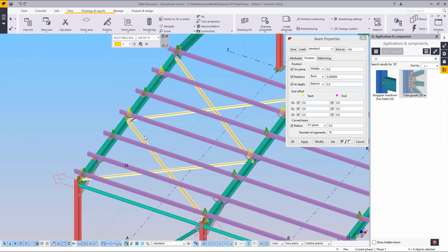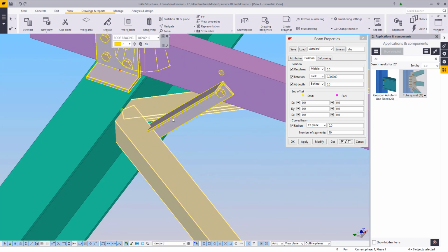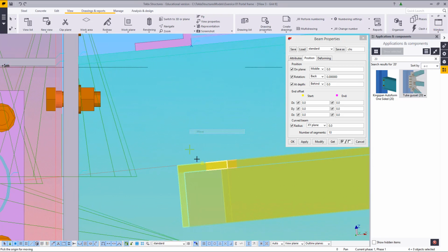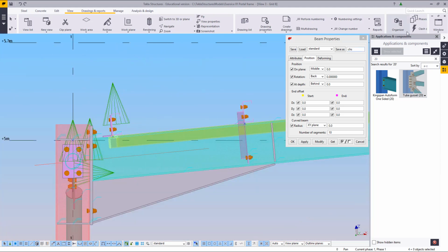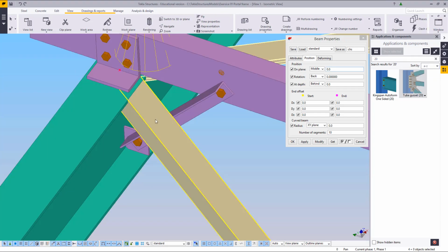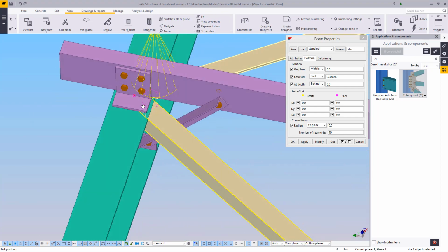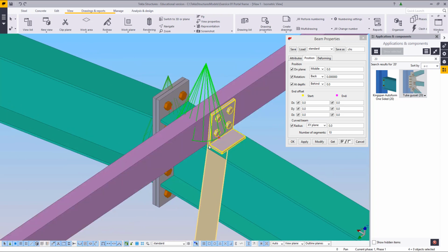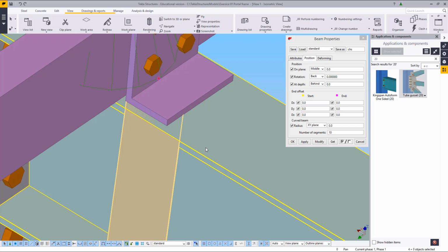Now, the main problem here is normally I would put them back to back, but we have a kind of clash here with the knees. In this case, I'm going to take them and move them up right against the top. If we look at the isometric, you'll see that this way they clear everything. Now, unfortunately, I can't leave them here, as the gusset plate will have to be on top of the rafter, which won't work, especially not because of these cleats.